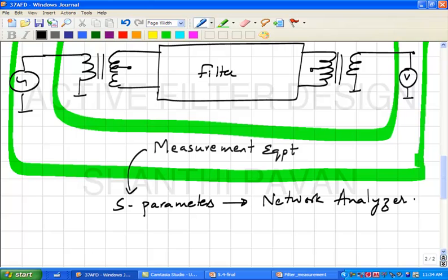All right. So, the network analyzer is a box which, I mean, we want to characterize this across frequency, correct. So, what do you think must vary? What the analyzer is doing is varying the sinusoid frequency, and for every frequency measuring the 4 parameters of the 2 port by measuring the voltage and current at the edges of the box. It is a box, right, it can only measure stuff at its entrance or exit, you understand. It does not know that your filter is 2 miles away, connected to the box through cables.